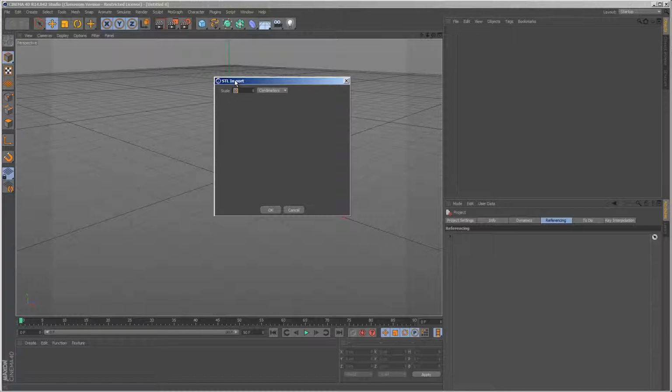You had asked me about whether this comes in as the right scale, and it's hard to tell because STL files can't carry scale information with them. So when you export an STL file, the program you're using will usually ask you what scale to use, and then you have to tell me what scale you used to export so I can choose the same scale on import. There's no way for that to carry with the file.